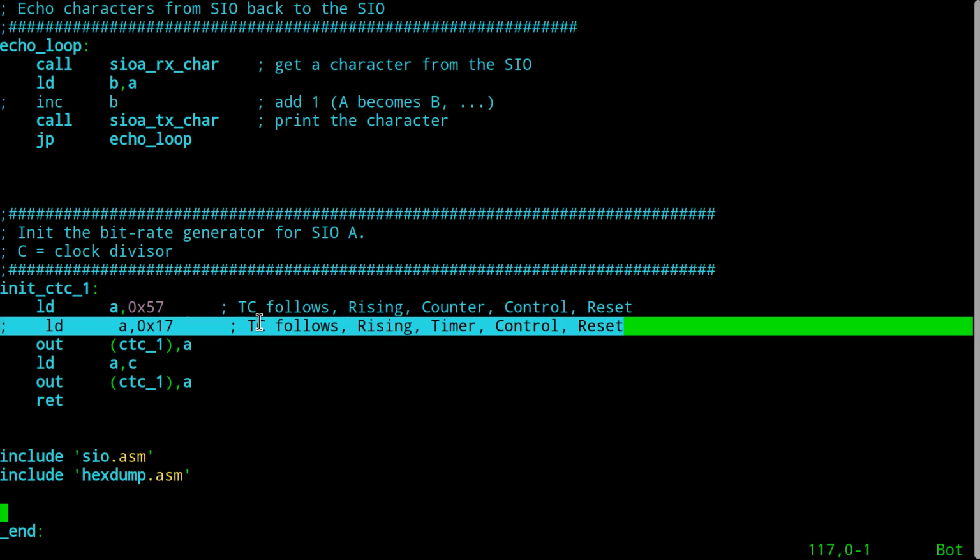And by the way, that's a very common thing to do back in these days because these oscillators cost a lot of money, relatively speaking. Okay? So it was not uncommon to run your Z80 at some wonky speed because it was convenient to be able to use the same oscillator or crystal, if you built the oscillator yourself, as the serial data rate divisors were needed. Okay? So I give the option to do that or not to do it, okay? So you have both choices here.